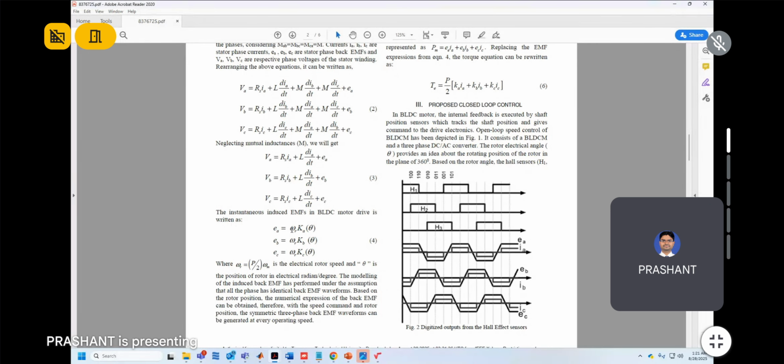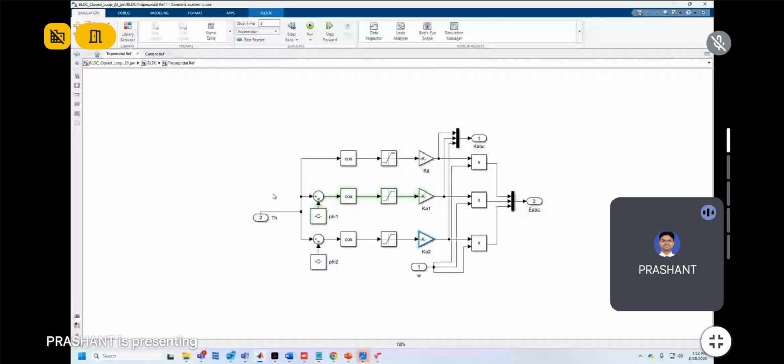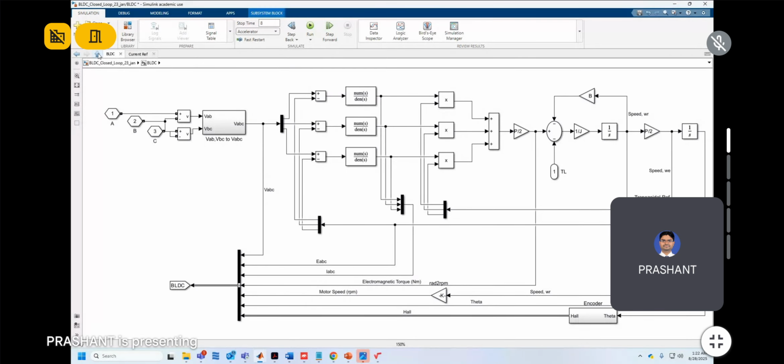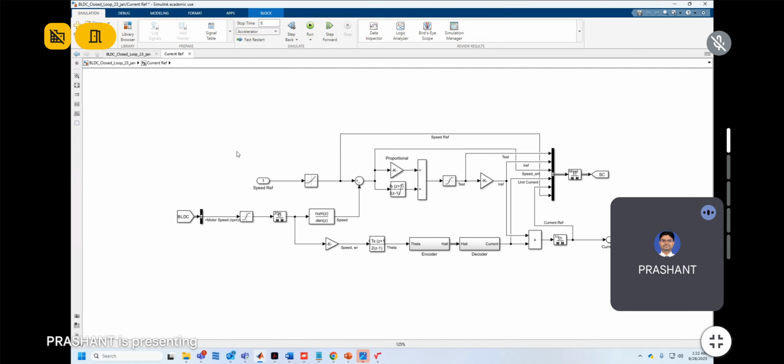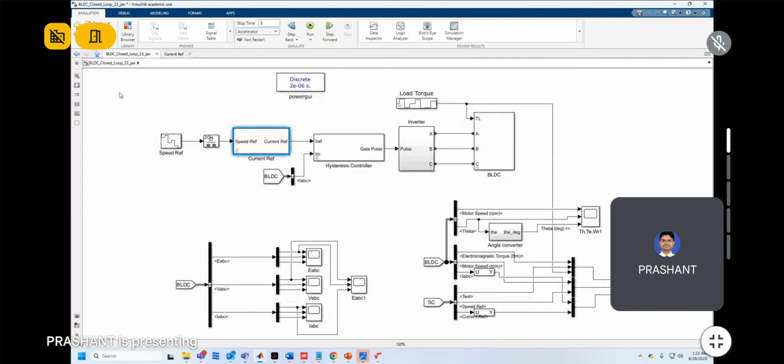See here, EA. So we were multiplying the rotor mechanical speed with some phase back EMF constants to get EA, EB, EC. And I will also explain why I am using cos and sine. This is for some compensation angles. Now, giving some reference speeds and generating the current reference.